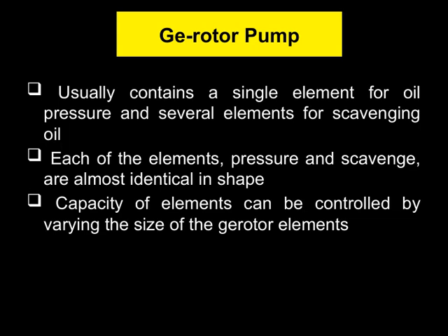On this slide, we're looking at how the gerotor pump manages oil flow within the system. Usually, there is a single element dedicated to controlling oil pressure, which is crucial for maintaining proper system function. In addition, there are several elements responsible for scavenging oil, and these are designed quite similarly to the pressure element. The shape of these scavenging elements is almost identical, which helps streamline manufacturing and maintenance.